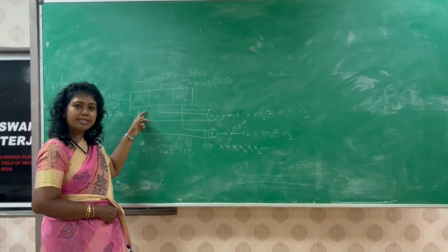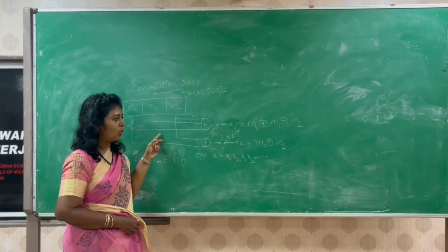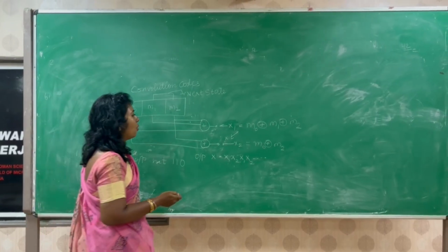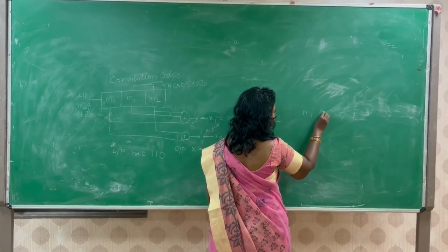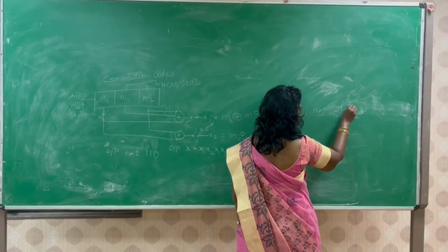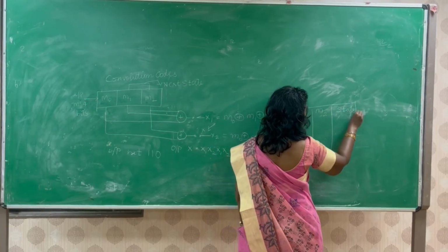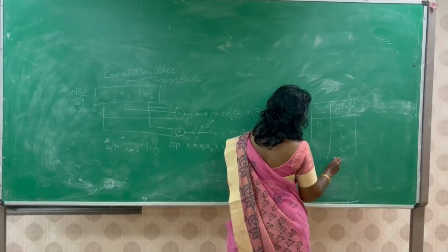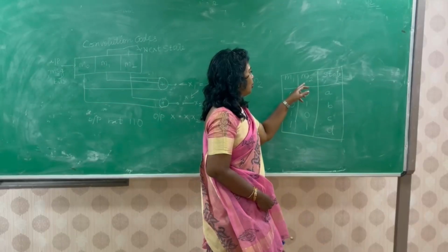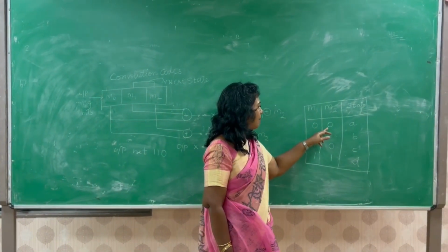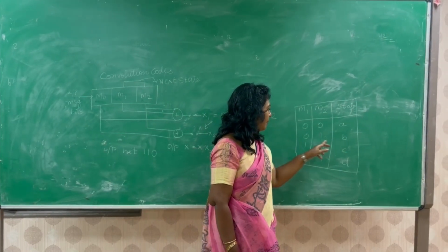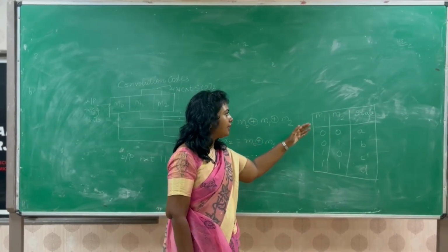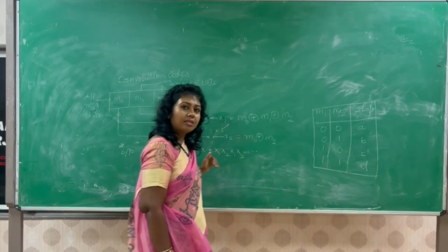Now, let us see an example with an input of 110 given to the shift registers, and we will see how we can construct a code tree and trace the code for this example. Now, as I told you, M1 and M2 are the two registers which represent the next state. If the contents of registers M1 and M2 are 00, that is state A, 01 is state B, 10 is state C, 11 is state D. So having an understanding of how the registers operate and what the different states for the contents of M1 and M2 registers are, let us start designing a code tree.